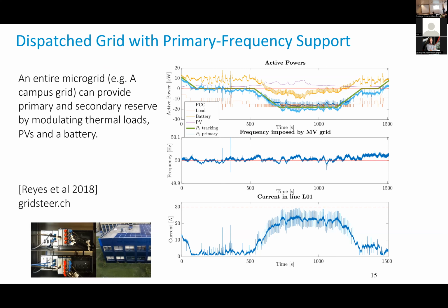So when that happens, primary frequency control, the droop control says we should slow down the generator, we should produce less. So here we do it synthetically, and the converse happens here when the frequency is lower, we produce a bit more. So that's music of the future. Here it's more or less experimental things, but we think that in the future there will be markets and opportunities for using power electronics to provide also some frequency support by adjusting. Of course, you need an adjustable source, which in this case is a battery.